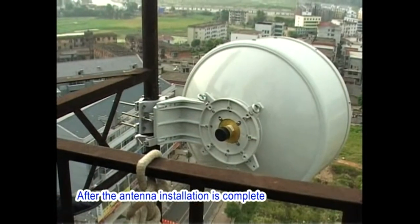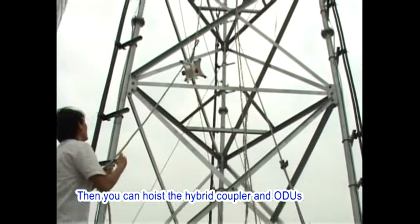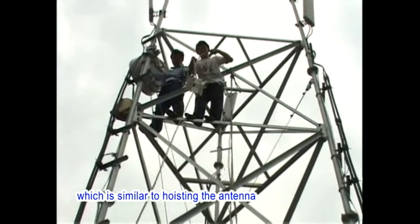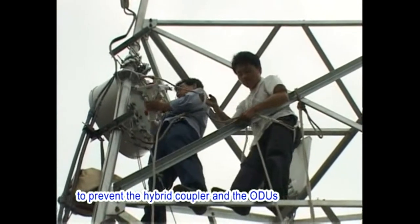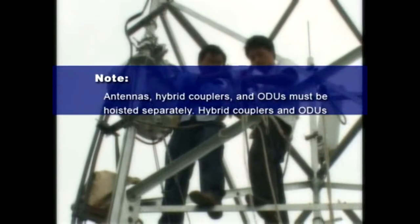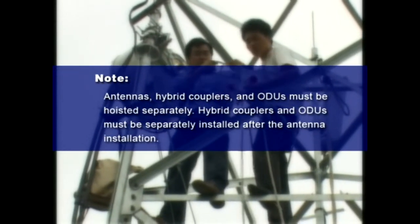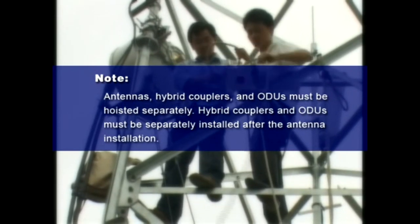After the antenna installation is completed, remove the 2 rubber plugs at the bottom of the antenna shield. Then, you can hoist the hybrid coupler and ODUs, which is similar to hoisting the antenna. The pulling rope is required during the hoisting to prevent the hybrid coupler and the ODUs from colliding with the iron tower. Note: antennas, hybrid couplers, and ODUs must be hoisted separately. Hybrid couplers and ODUs must be separately installed after the antenna installation.